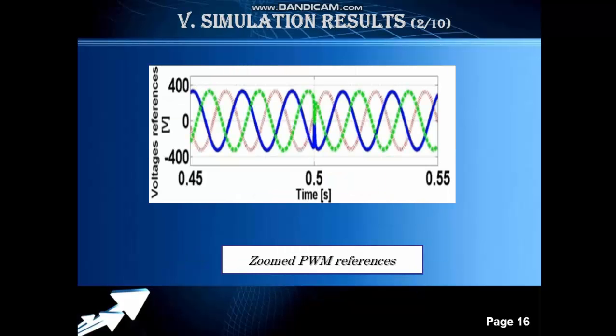The following figures show the references of the inverter output voltage. We remark here that the curves of the reference have a sinusoidal form without distortions and fluctuation, signifying that the PWM outputs will not contain very fast variations. Therefore, these outputs will not saturate the inverter switching and will not lead to unwanted heat generation in the level of the inverter.